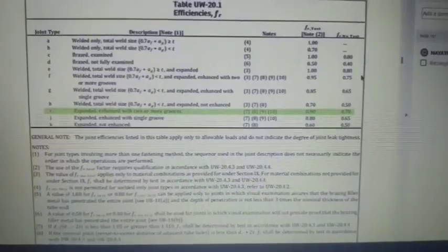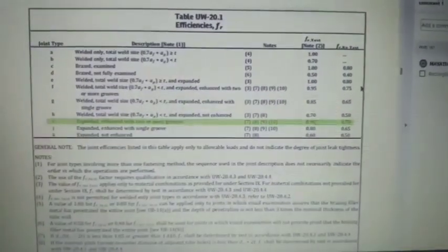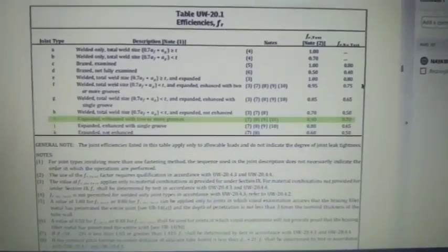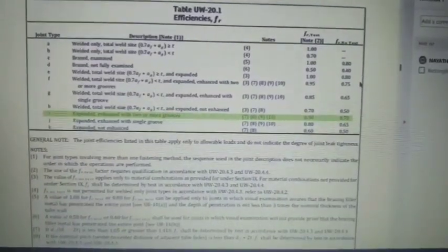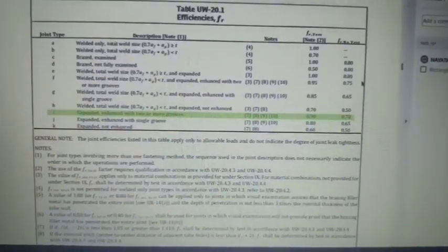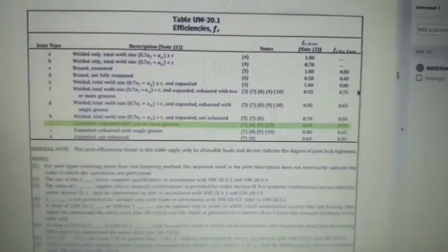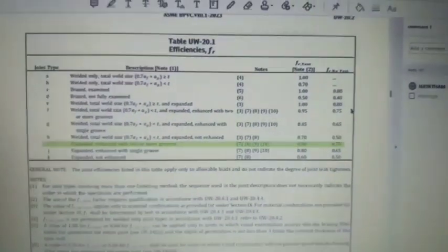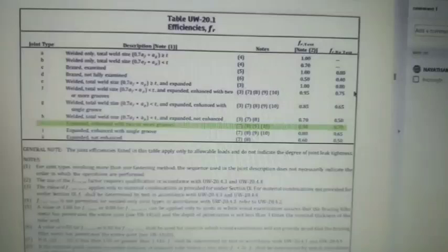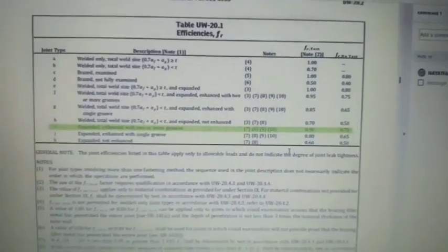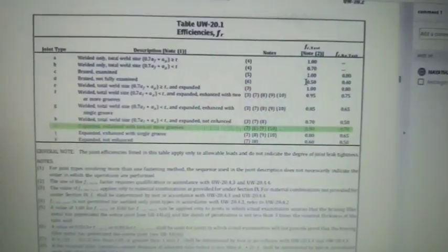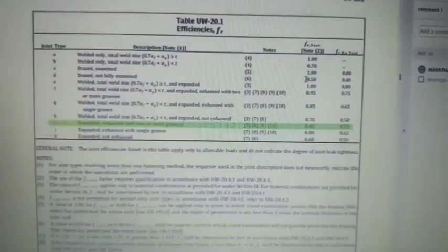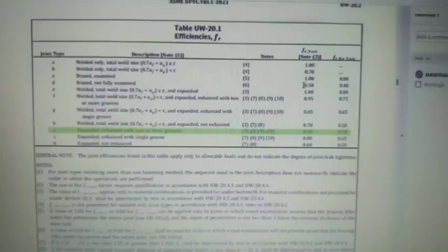Now, what is the problem happening in the log? Now there is a mention of the factor Fr. If minimum Sy or Syt, or 1 for expanded joint, when Fr is less than 0.6, qualification of joint by shear load test is required. Otherwise not.